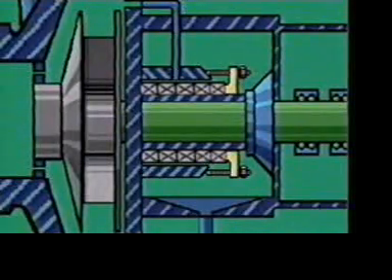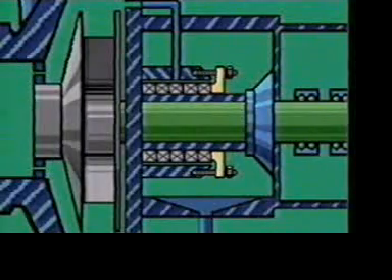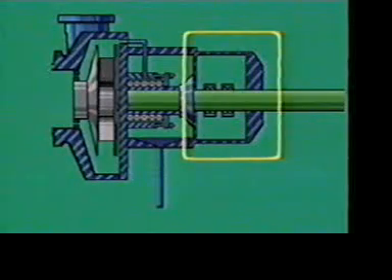A gland follower is also found with the stuffing box. Basically, it's a bushing designed to hold and compress the packing gland in the stuffing box. Bolts usually hold gland followers in place. They're also used to adjust the gland follower's position. These are bearing housings. They support and protect bearings. There are different types of bearings. We'll look at them and their purposes in section 3.